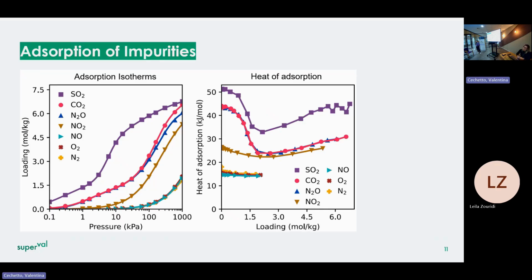If there are the rest of these gases, they are not a problem, but the mixture generates the acids that are a problem for everything. This is what we have experimented. So the NOx is no problem, but if there's humidity in combination, then it's a problem for the long-term stability and the performance. We get some permanent damage. It's not completely destroyed, but there are areas of the material that are decomposing.